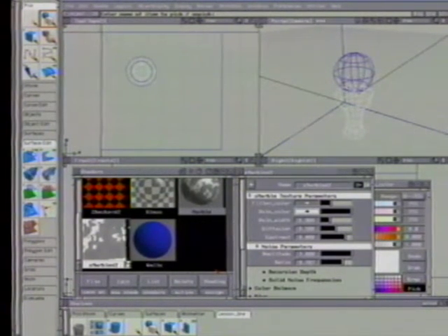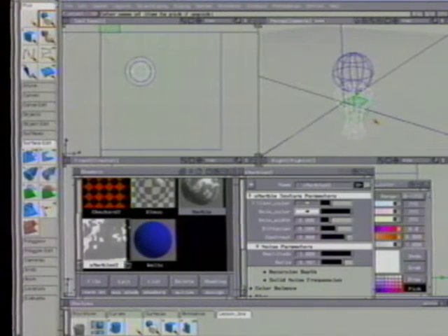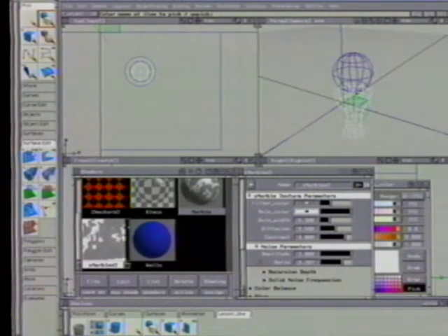Positioning a solid shader is different than a surface texture. With the solid texture, you need to position the shader in 3D space in relation to the actual object. In the shader lister, click on the little icon at the lower right of the solid texture. In the modeling window, you now see a positioning object at the origin.